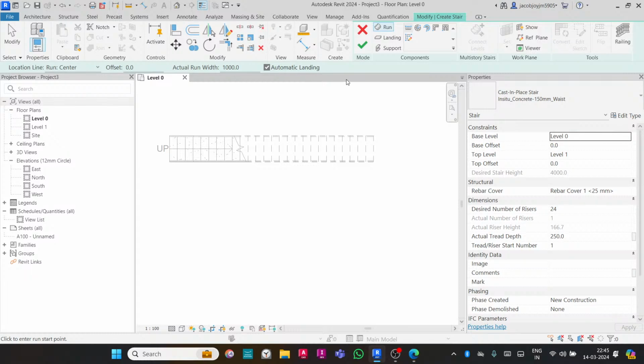I'm checking the options and the instance property. If you want to make a change, you can do the changes, and then click on the first point, and you see below it's showing 15 risers, 14 risers created, 10 remaining. You can also see how many risers created and how many remaining.